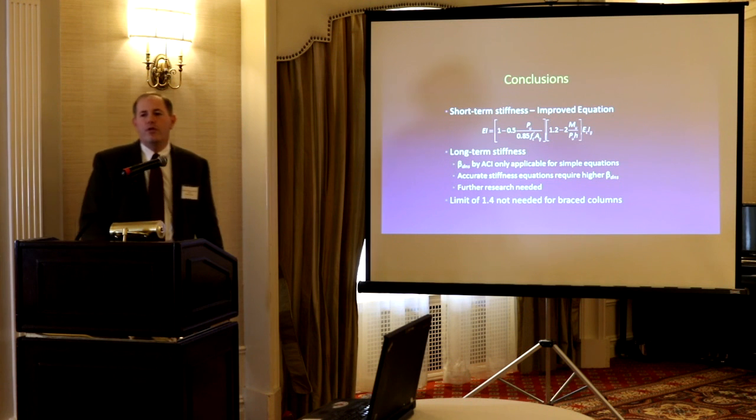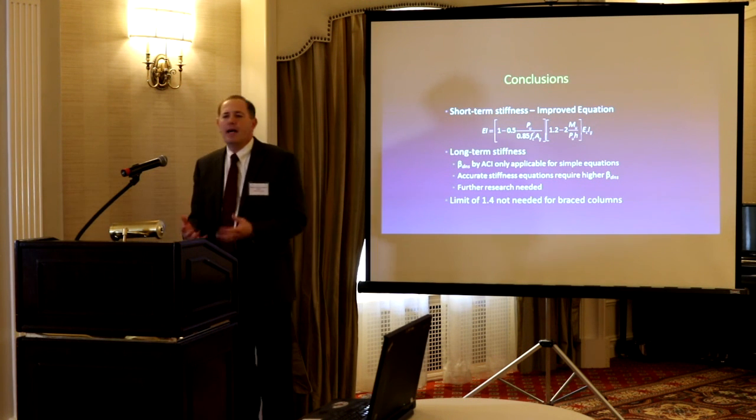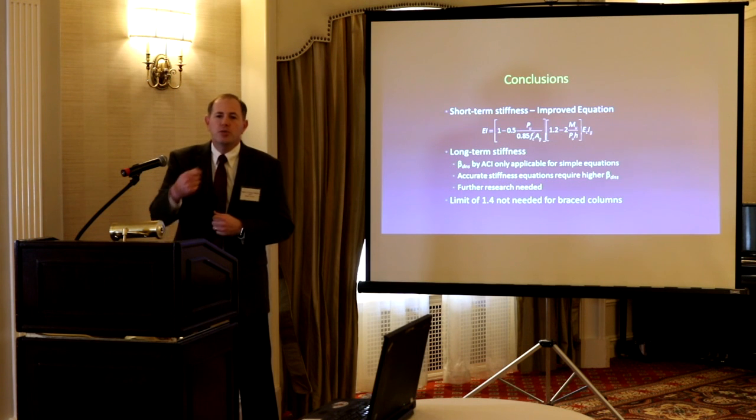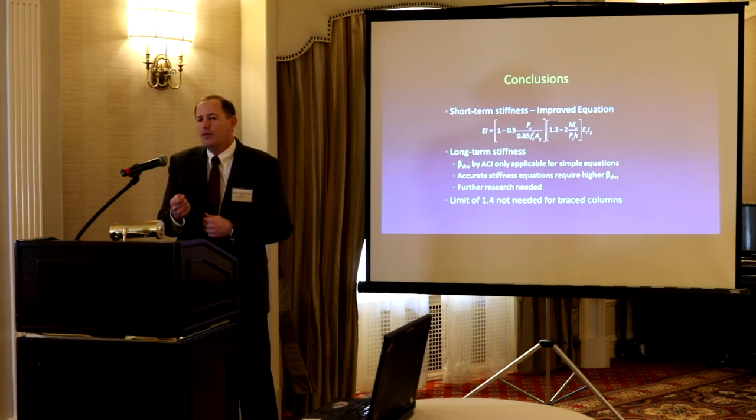The limit of 1.4, I didn't spend a lot of time on that. It's not needed for the braced columns. We can predict what these values are, how much moment is happening, regardless of the level. So we don't need a limit in the code for the non-sway case.